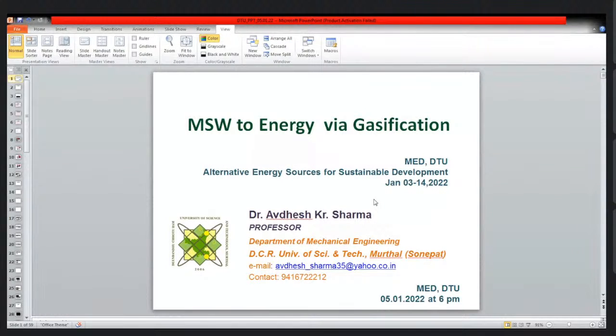The mixture of producer gas and air, when it is compressed, we need to make a spray over it so that the ignition will take place. And it is a very minute quantity. If we are using 100% gas in a diesel engine, it is hardly 25, 20 or 15, or sometimes only 10%. And if we add biodiesel in it, again 20% of biodiesel can be substituted in diesel, so again there is a saving of diesel.